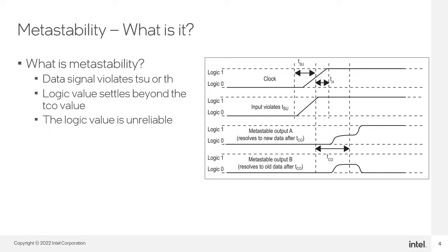If the data output signal resolves to a valid state before the next register captures the data, then the metastable signal does not negatively impact the system operation and there is no design failure. Note that the designer must use proper design techniques to handle asynchronous signals or signals crossing clock domains. We'll talk more about this in a little bit. If the metastable signal does not resolve to a low or high state before it reaches the next design register, it could cause the system to fail.